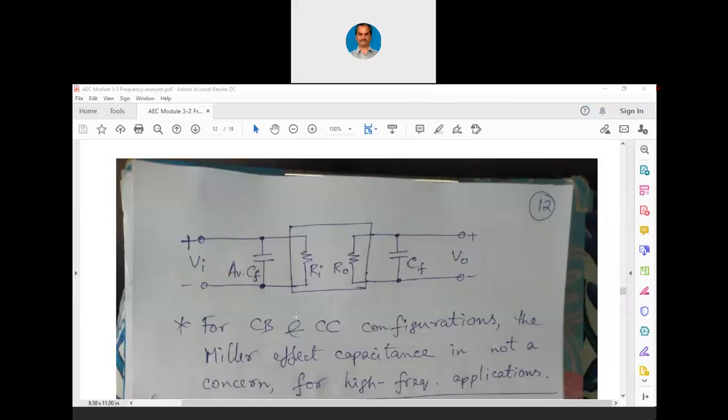in JFET, just like we have a common emitter configuration in BJT, we have a common source configuration in JFET. There also, between gate and drain, that junction is reverse biased. Please visualize that pinch off region and visualize the structure of the JFET, which I had shown earlier in a three-dimensional way. So that gate to drain junction itself is reverse biased.